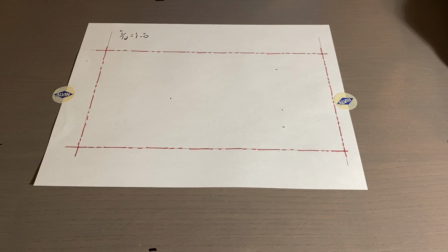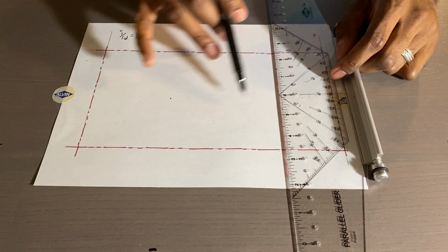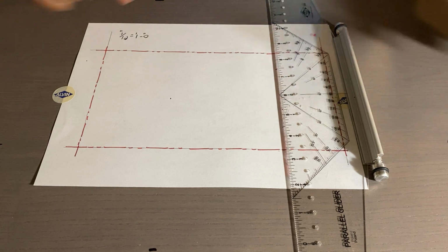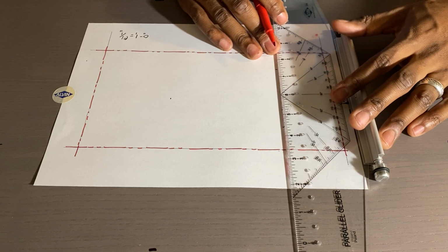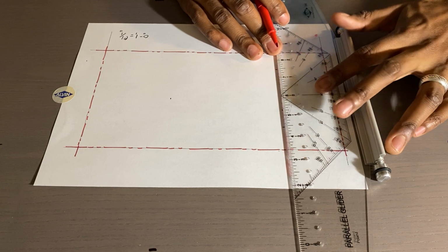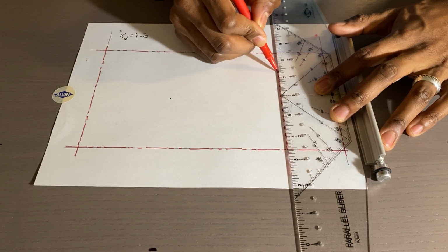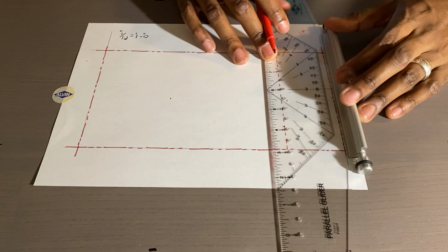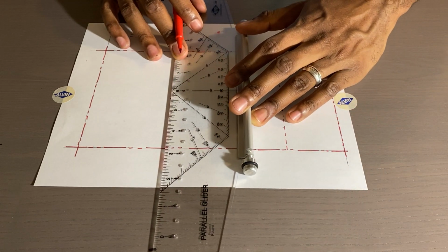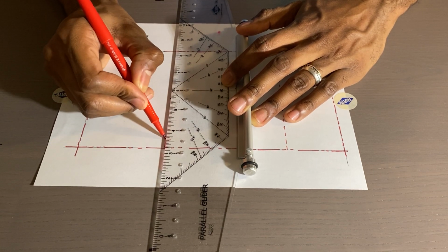So now that we've established our lines, we once again take our sliding rule here, and I'm gonna skip the light line step, please by all means do it yourself if that makes you feel more comfortable. But for the sake of this tutorial, I'm just going to skip that step so we can get to the good stuff. So draw my 20-foot line here in the front. That's my front setback, 20 feet. And then try to play by the rules here. Then this is my 30-foot setback from the rear lot line. So I'll just dash that in.